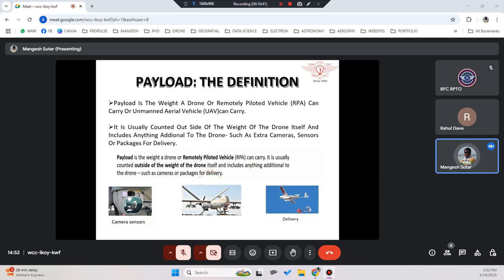So when I design for 50 kg, the utilization of the drone will always be divided by 2. I design a drone in such a way that every propeller or every motor is capable of providing a thrust of 12.5 kg. So four propellers, 12.5 into 4, will be 50 kg. But what would be the maximum takeoff weight for my drone? It will be the total thrust provided by all four propellers divided by 2, so that will be 25 kg. Any drone you design is supposed to be designed that way.